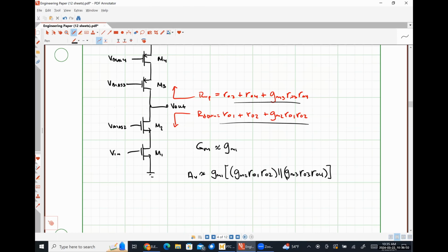If we had a really long transistor, we would have a lower channel length modulation coefficient and all of that kind of good stuff. So for BJTs, it's very obvious to say, well, as an integrated circuit, practically everything is going to be matched. For a MOSFET, we have to physically do that ourselves. So you may not have everything nice and matched, and so pay attention to the subscripts. All right, that's cascode amplifiers.